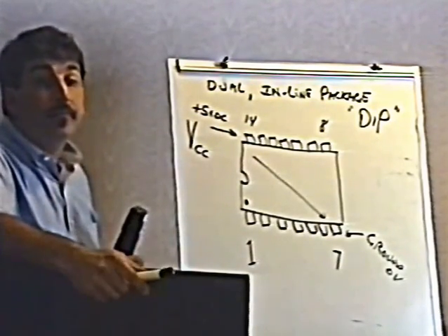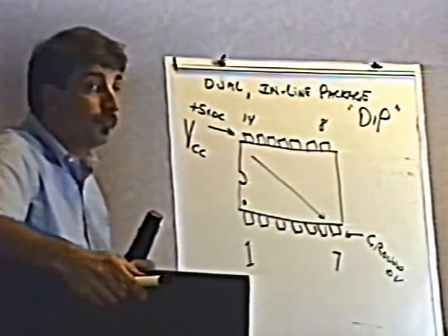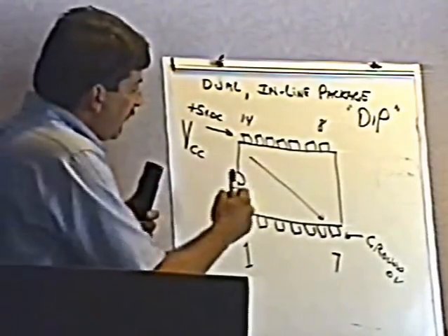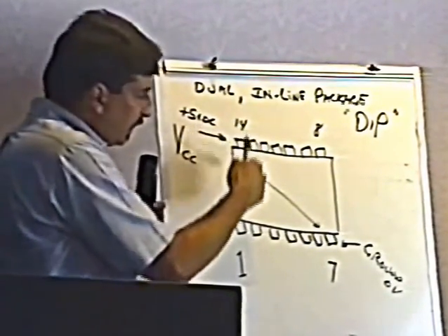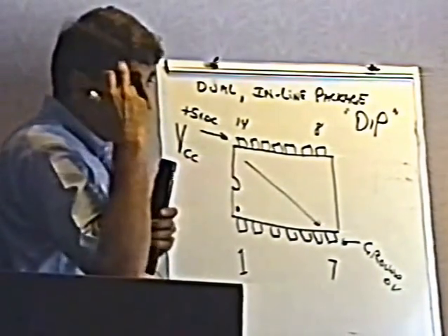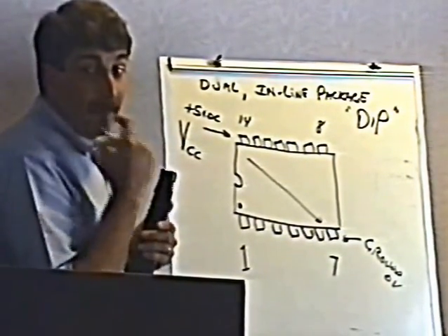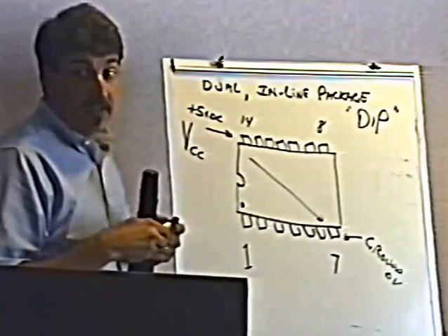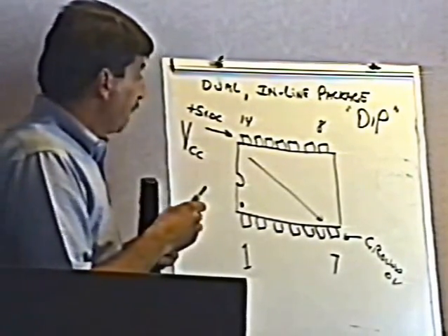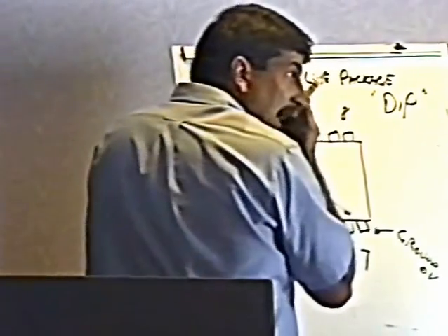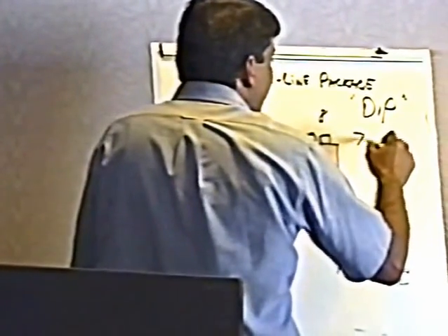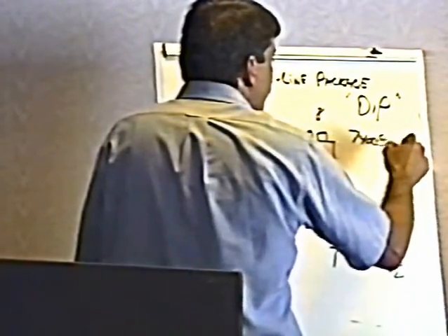Now, yeah, go ahead. Basically, the power is always opposite the dot. The 5 volts is always right above the notch. Holding the notch to your left, it's always right above there, or almost always. Now, specifically, there is one type of integrated circuit that I do look for. We have a family of integrated circuits that we use in games, and it's known as the 7400 series.